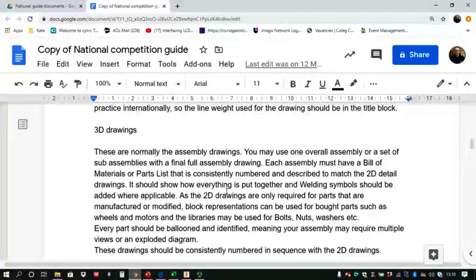So you might have a sub-assembly that uses part 001, part 002, part 003. You then can't go on to a main assembly with part 001, 002 and 003. It would have to refer to the sub-assembly, which might be called 004, it might be called sub-assembly 1 or sub-ass 1 or any of the other things. But when you actually put it in, it needs to be consistent. So if we refer to sub-assembly 1, we can go to sub-assembly 1 and see the parts that are in it, and then when you put any new parts into the main assembly along with the sub-assemblies, they should not have the same numbers, and no two sub-assemblies should have the same numbers. So each number for each part needs to be unique.